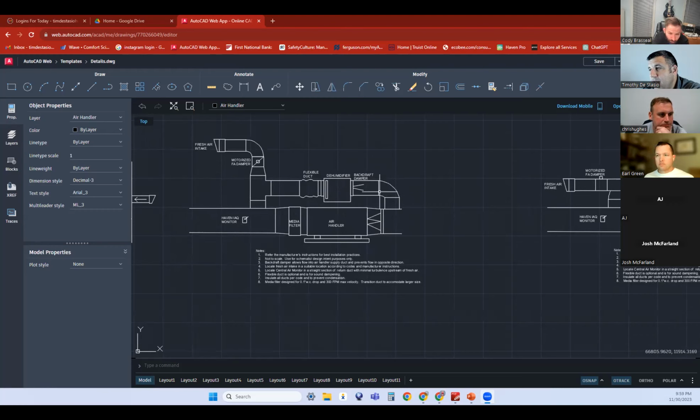Santa Fe is suggesting that we dump it into a 45-degree angle. Again, this dehumidifier has to fight this static pressure, has to push against it. And the Santa Fes have a beefy enough blower that can do it. But I can tell you other brands that don't. A lot of other brands will have you pull from the return and dump back into the return because they know good and well their fan can't overcome the static pressure.